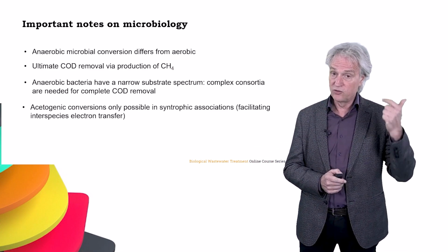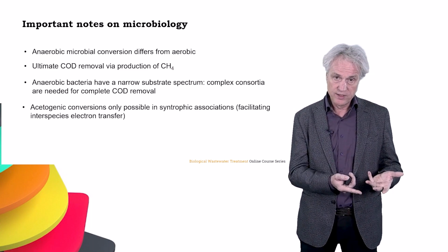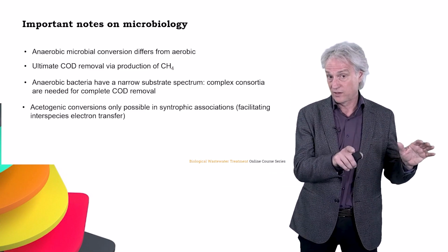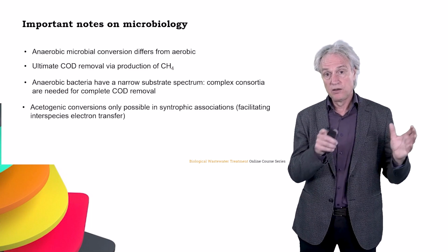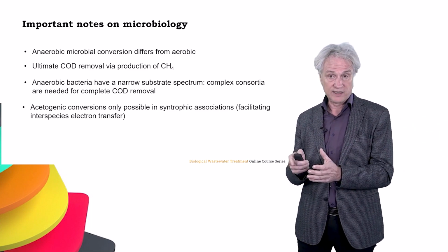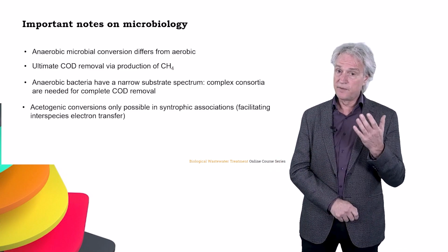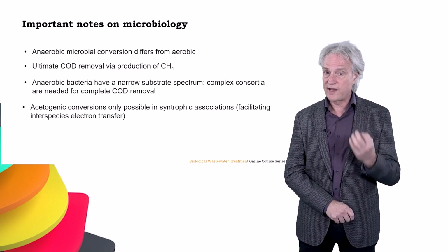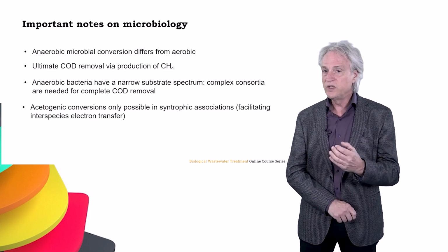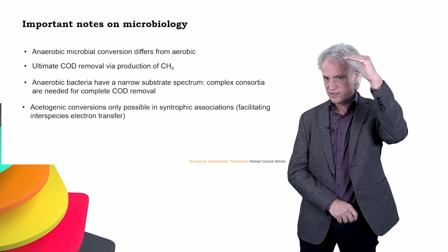Under aerobic conditions, do remember, you destruct the COD with oxygen, and COD is gone. Here we in fact recover the COD from the complex compounds that we start with to methane gas as an energy carrier. Another big difference with aerobic technology is that anaerobic bacteria have a very narrow substrate spectrum. So we do need complex consortia for complete COD removal. And do remember the steps that I mentioned.